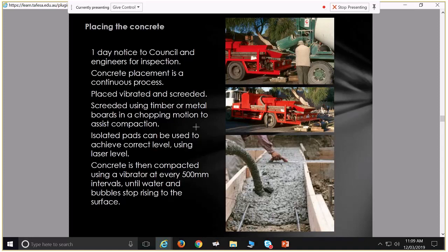If we put more cement in, well then that concrete is going to be stronger. Or if we put less water in, that concrete is going to be stronger. But the thing is, if we put less water in, then the concrete's not very workable. That's fairly high slump concrete. We can see that by the way it's pouring in there. It's very liquid. And what we're talking about when we talk about slump is we'll have a cone, fill that cone up with concrete, tip it down like that, and lift it up, and it goes out like this. It pours out flat. That's really high slump. It's slumped a lot. If we lift up that cone and it stays there, that's very low slump. Low slump concrete is very hard to work. It's hard to get it into all your forms.